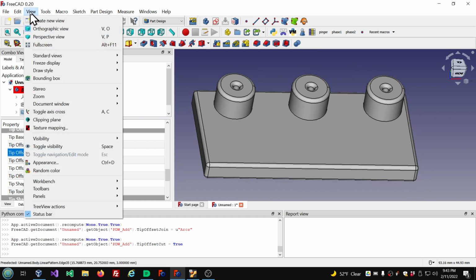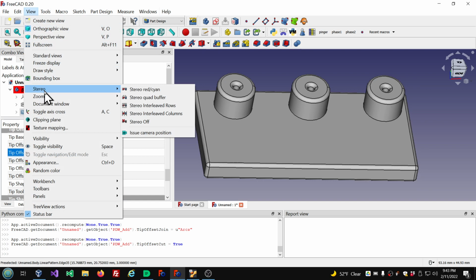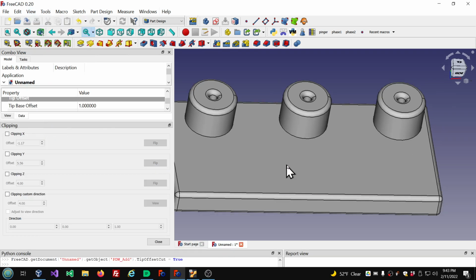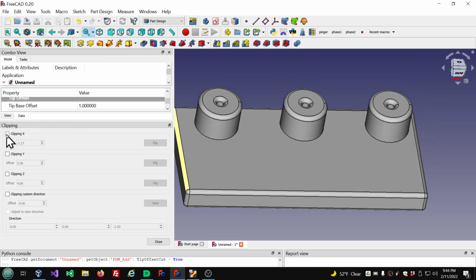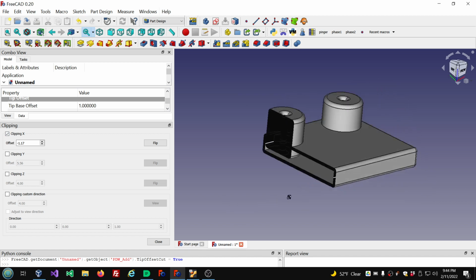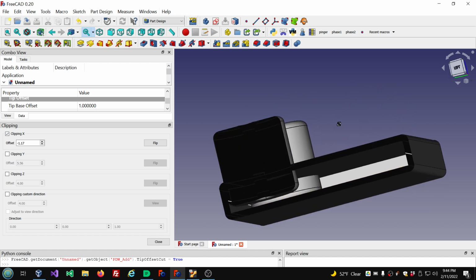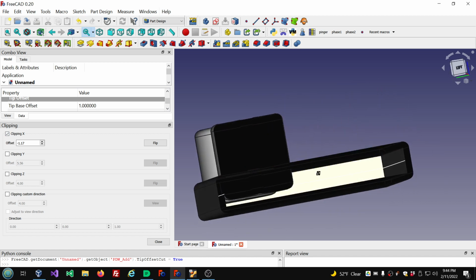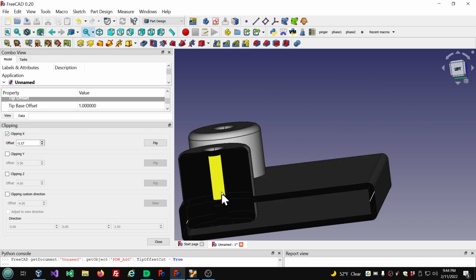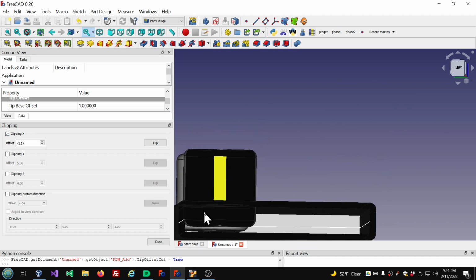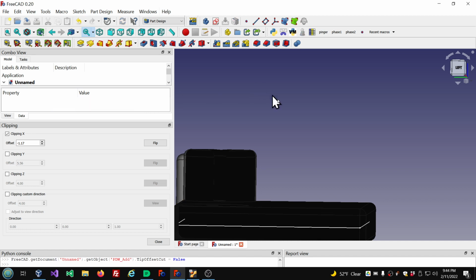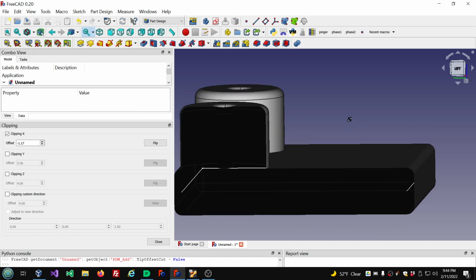And if we use clipping plane, you can see here, can you, that the inside was cut out of these by having offset cut set to true. Set it to false, and it's not cut out anymore.